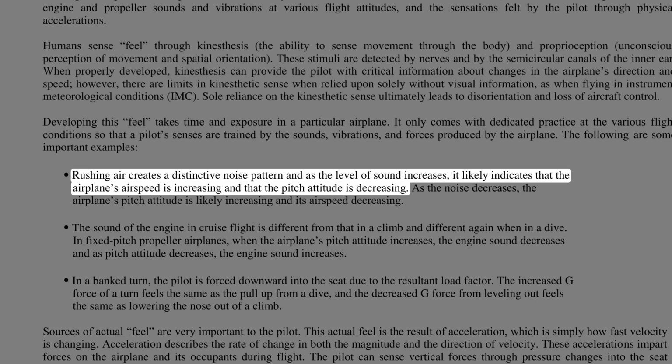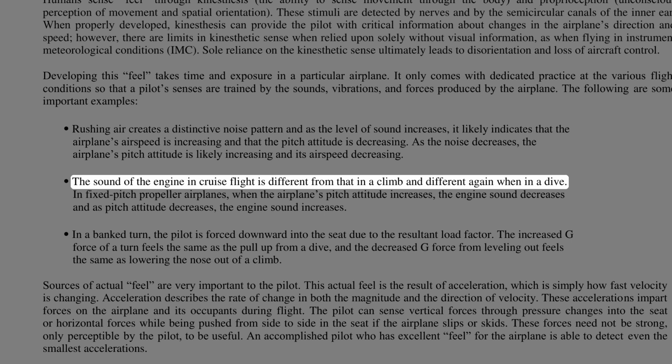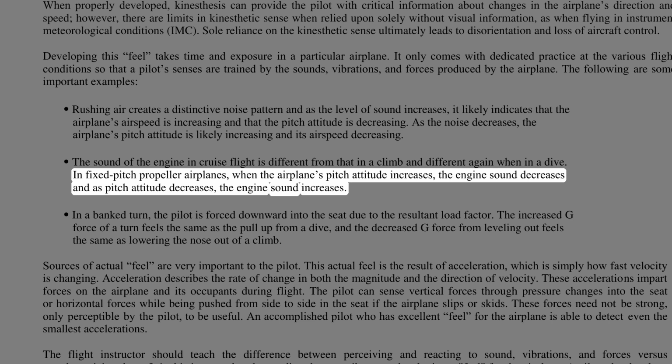Rushing air creates a distinctive noise pattern, and as the level of sound increases, it likely indicates that the airplane's airspeed is increasing and that the pitch attitude is decreasing. As the noise decreases, the airplane's pitch attitude is likely increasing and its airspeed decreasing. The sound of the engine in cruise flight is different from that in a climb and different again when in a dive. In fixed-pitch propeller airplanes, when the airplane's pitch attitude increases, the engine sound decreases, and as pitch attitude decreases, the engine sound increases.